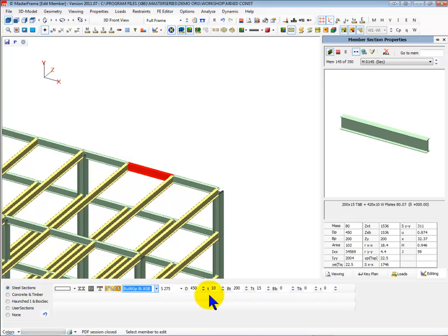And obviously I cannot haunch it because it's not a uniform, it's not a standard member. If you wanted to then haunch that, you would have to go and create it in the open library to get it to design it as a steel member. So that's the only way to design a tapered eye section, would be to create it in the open library of steel sections, bring it in here, put its tapering on then, because we cannot taper these built-up sections.